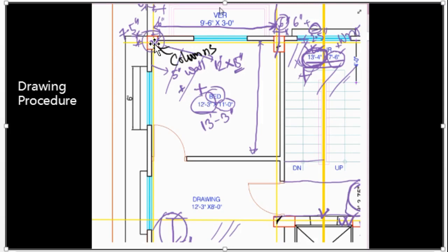As you know, from 6 inch offset from this intersection, if you draw a line, that will be the outside brick line. And if you take 1 inch offset from this intersecting point and take a line, that will be the inner wall side line you will get.